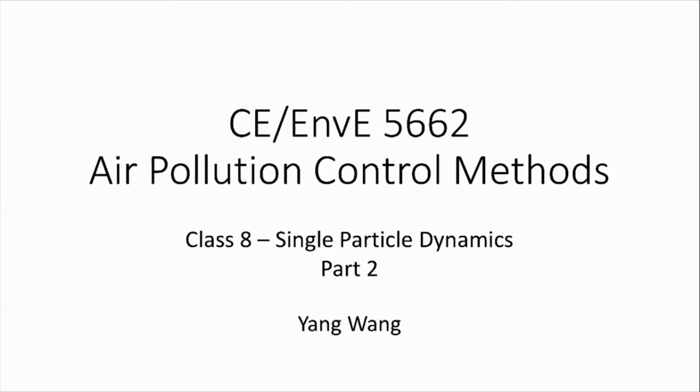And then we can also use the centrifugal force. Basically, it's called a cyclone. We're going to know that very soon. Okay, so cyclones are basically a cylindrical device where you push the airflow to rotate, right? To basically revolve around the center axis. So you will have a centrifugal force. Then the larger particles will just get spun to the outer wall of the cyclone. And we also will know the electrostatic precipitator, which uses electrostatic force.